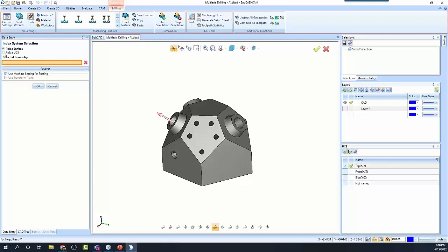Depending on the post processor and the machine configuration and the different formats for posting like coordinate rotation, it becomes more important to use a coordinate system, so this way you can establish your X and Y direction as well.